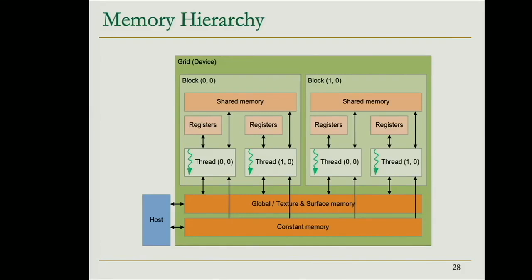So we have, assuming, for example, blocks of only 2 threads, these 2 threads. Each of them can access their own registers. Recall the pipeline register file where we have the different SIMD lanes, and we have the whole register file that is partitioned, and part of this register file, a certain number of registers, as many as they need, are assigned to the individual threads.